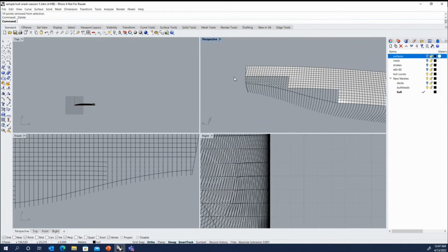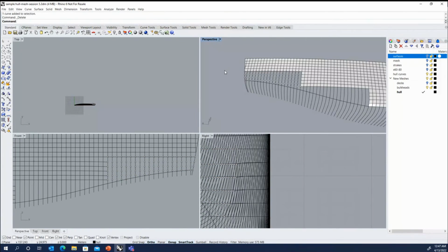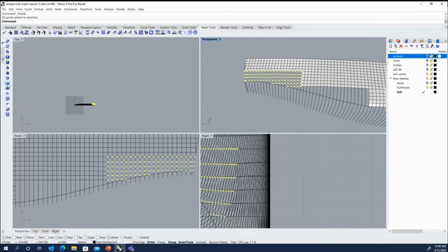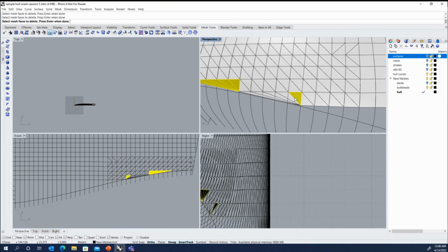And then we can create the mesh from there. Get rid of that curve so we don't use that as part of our mesh. Now, we know we have a stepped mesh here, but when it goes to create the mesh, it's going to close those in. So we'd have to manually go in and get rid of these extra pieces at the steps.